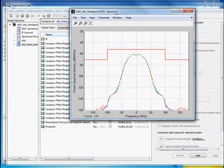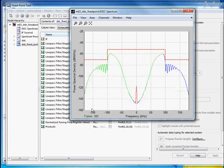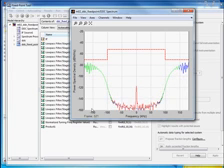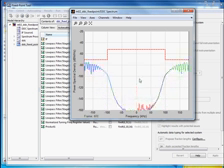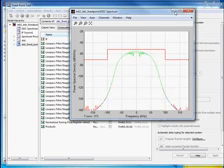So what we can do now is accept those proposed fraction lengths. And then we'll see how that affects the simulation. In order to do that, we need to go back to the local settings at fixed point. So let's go ahead and rerun the simulation now. And now we're seeing much closer agreement, still some departure we'd expect, but you see that it's many dB below the region that we care about. So they're not really relevant to the response of the design. So that's just a bit of a highlight of what you can do within fixed point.